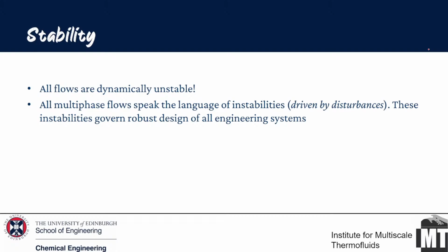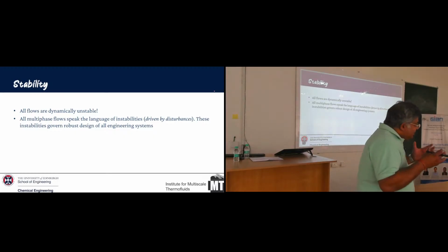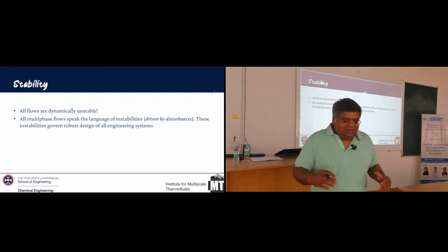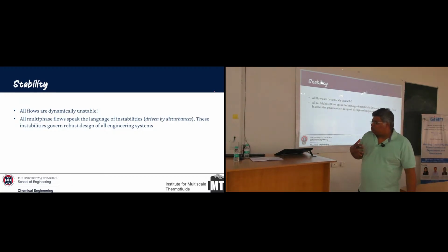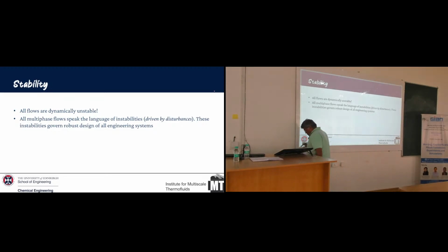Okay? I think this is my biggest complaint when you look at any CFD software, commercial, ANSYS, Fluent, whatever. The first example they will give you is two-dimensional, turbulent flow. There's no such thing like that at steady state. It's not possible. Turbulence is never steady. The very reason turbulence is difficult to study is because it is highly unsteady. Even if you have a supposedly laminar flow, it's a dynamic thing. It always moves. So there's no such thing as a stable flow.